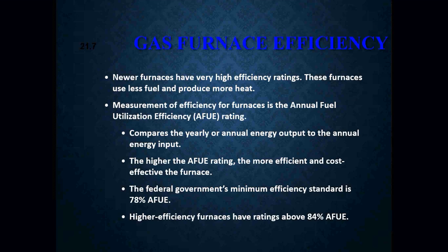Newer furnaces have very high efficiency ratings. These furnaces use less fuel and produce more heat. The measurement of efficiency for furnaces is known as the Annual Fuel Utilization Efficiency rating, or better known as AFUE. It compares the yearly, annual energy output to the annual energy input. The higher the AFUE rating, the more efficient and cost-effective the furnace is.